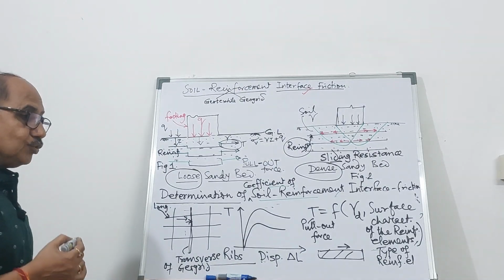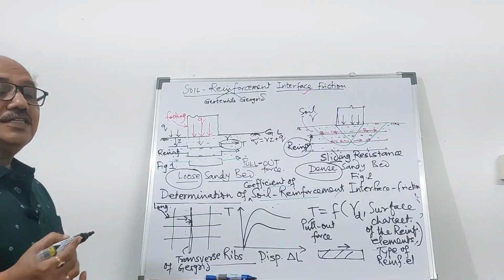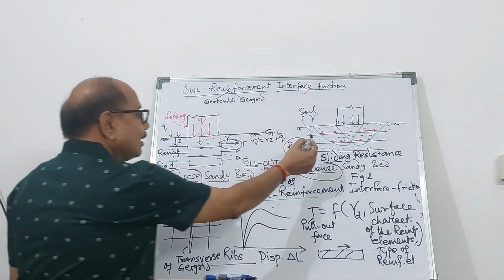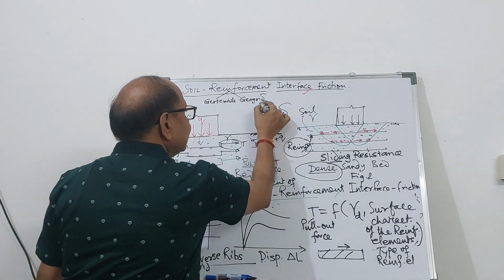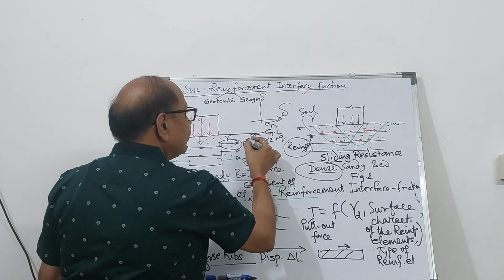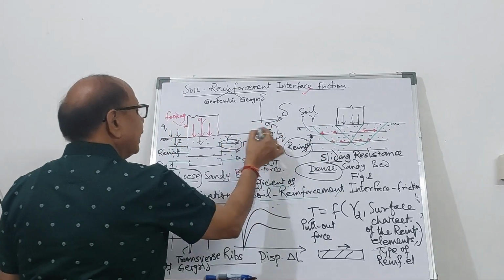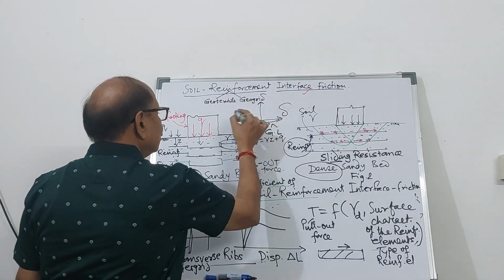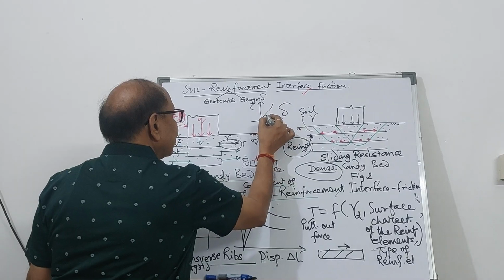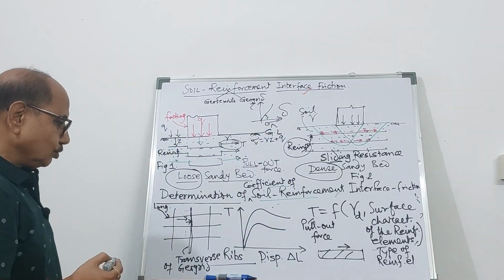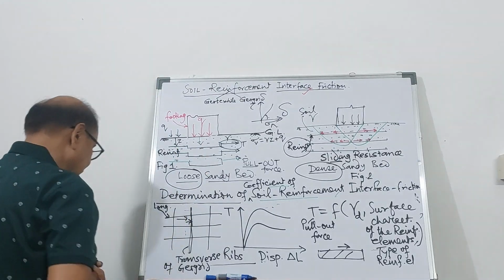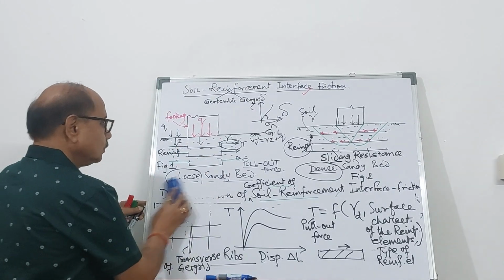And if you want to find out the coefficient of friction, here you have found out the delta value very easily by plotting sigma n, normal stress, and you have also found out the value of tau and then delta, as I have shown you. But here the pull-out, how will you calculate it? Let us see the pull-out.